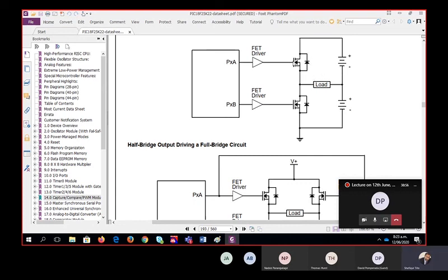So if you change the on time of these pulses, then this switch will be on for a small duration and your load will get the voltage for a small duration of that time. So I can connect the higher voltage through this switch, and this switch will work as an interface between the microcontroller and these high voltage devices. That is what we do in our industrial application.